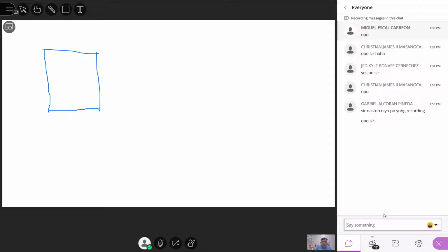Okay? So normally, ang prinsipyo ng slab is that a slab can be either a one-way slab or two-way slab. Tama ba? Ang sabi natin m, which is simply equal to the ratio of the short and the long span of the slab. Assuming that this is now the S, this is now the long direction of the slab. If m is less than 0.5, that is considered as what? One way, two way. Okay, if you recall, that is one way. Very good. Okay. So if it is greater than or equal to 0.5, then it becomes a two-way slab.